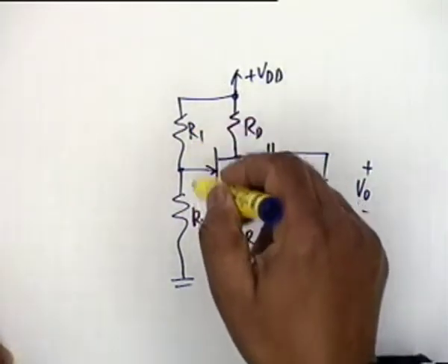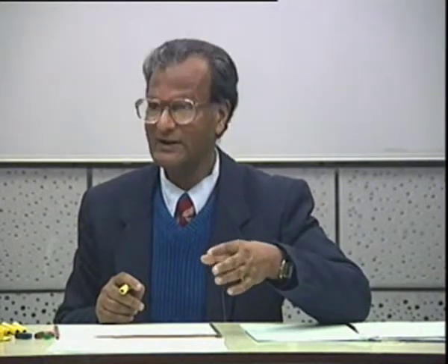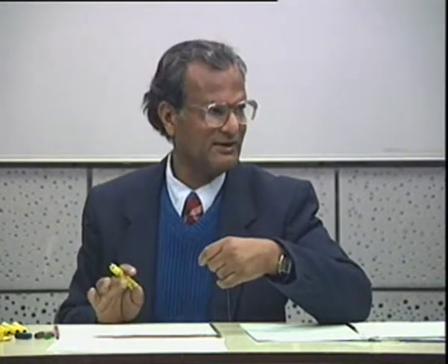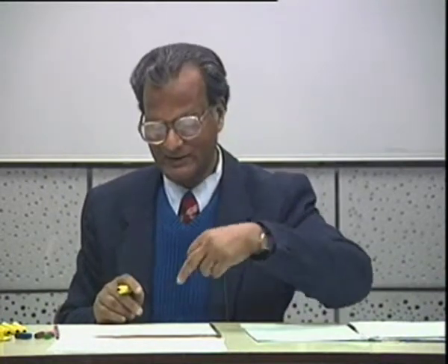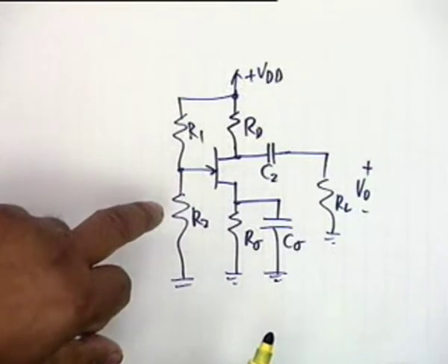The sole purpose of R1 and R2 is not to feed a current like a BJT. This must be understood. BJT requires a base drive, not voltage but a current, because otherwise I sub C shall be 0. I sub C is approximately beta times I sub B. But here this is not the case.